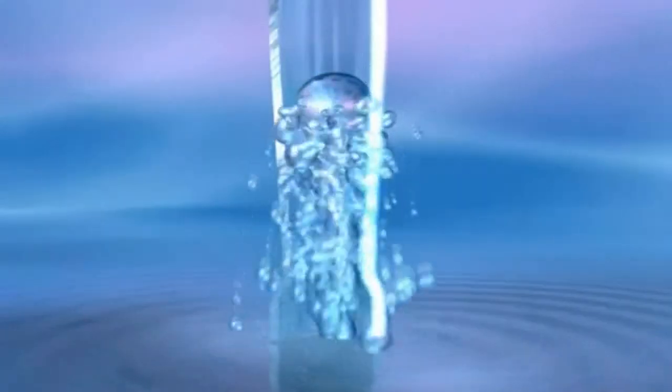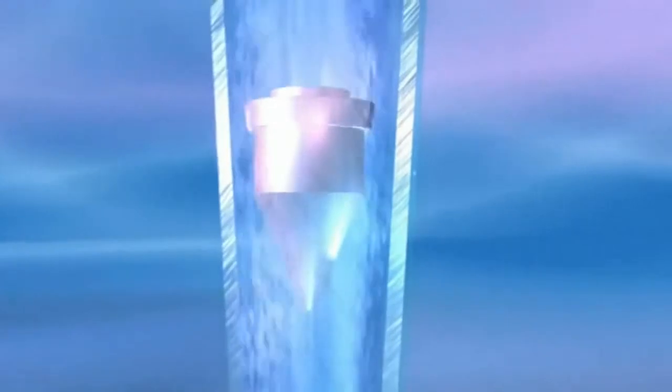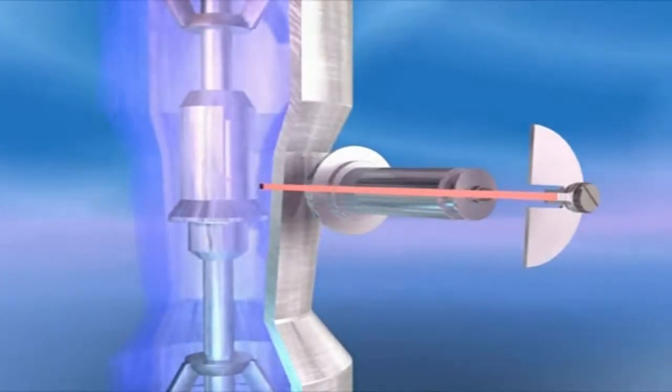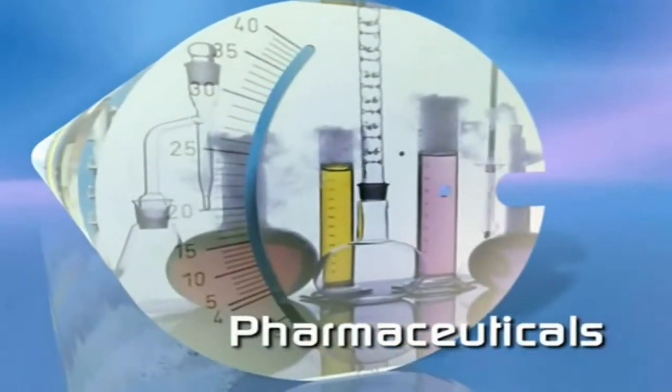Variable area flow meters are suitable for measuring liquids and gases. They have an upright conical tube in which a sophisticated float moves freely up and down. The flow through the tube causes the float to rise until the forces are in equilibrium. The flow rate is read off from the scale at the level of the float. The glass measuring cone allows direct reading of the float movement, whilst meters with a metal cone have a magnetic pickup. There is no need for external power for readout. For almost every application and industry,